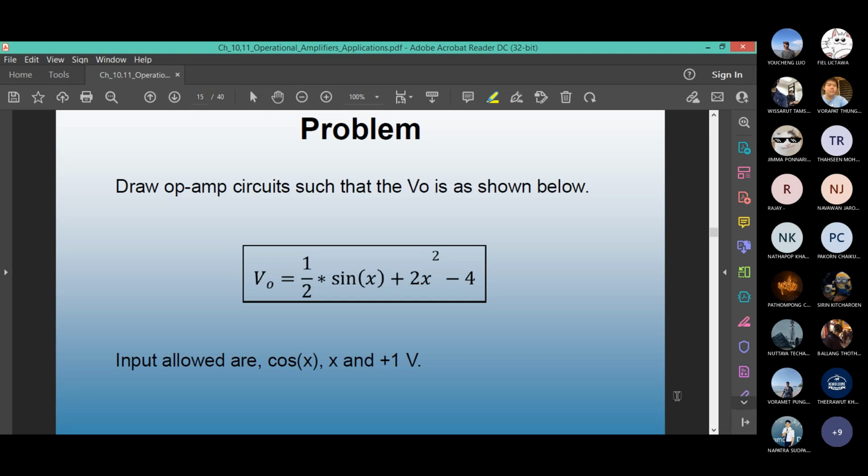You will be fine. But the way we did it in the class, we put an additional op-amp stage in the beginning with a gain of 4, and then on the output side we did a unity gain system.